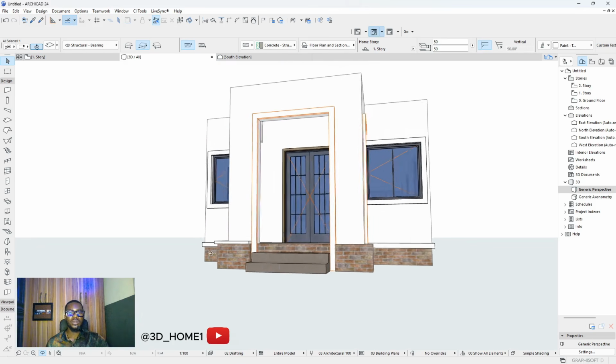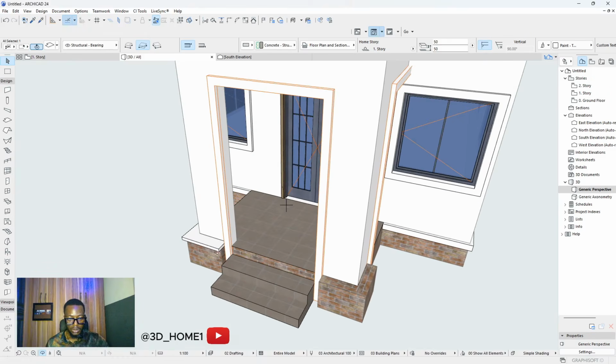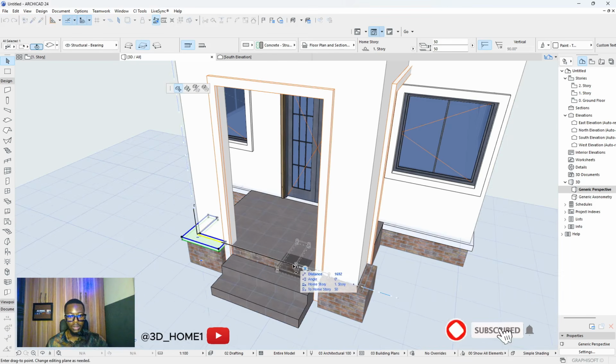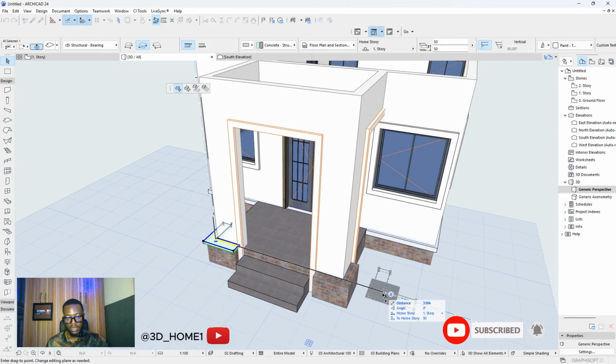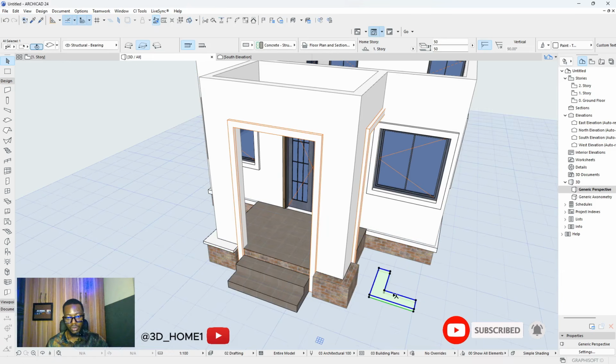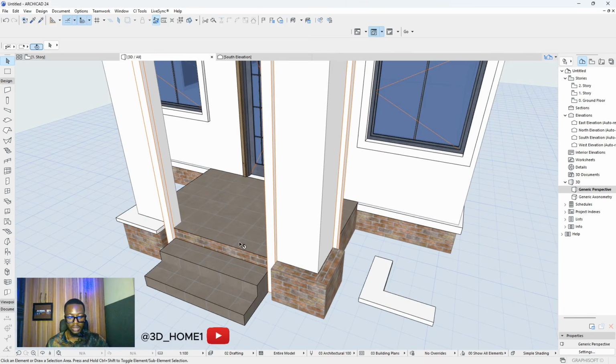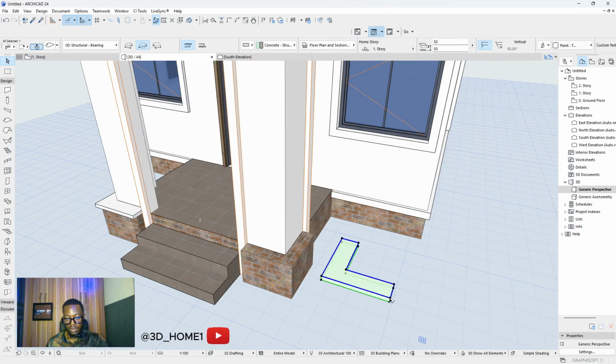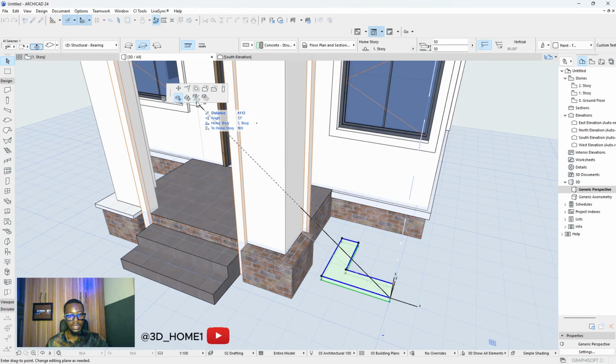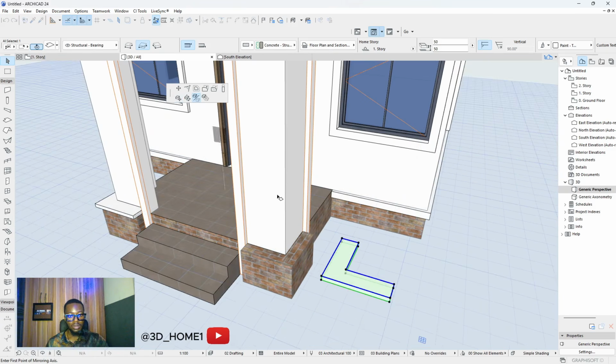All right, then you can either bring this one to this side or you do it again. So let's see if we can just copy it. Press Ctrl, click it, press down Ctrl, we have a plus sign, and drag it to this side. So now we'll just click on this one, this node, and let's say mirror.